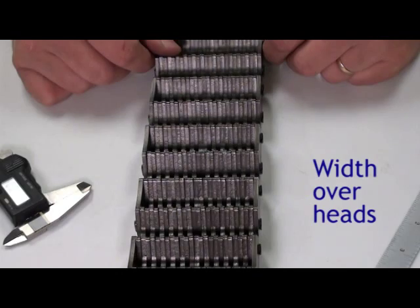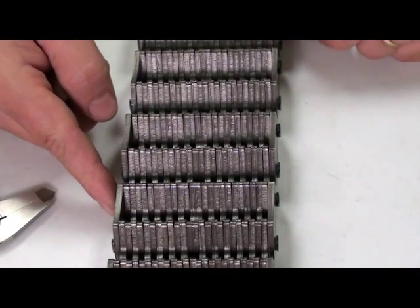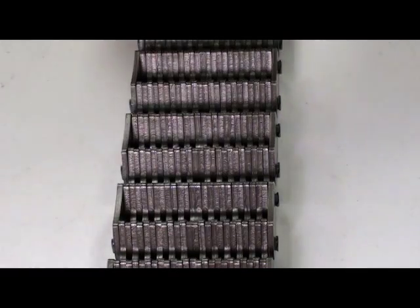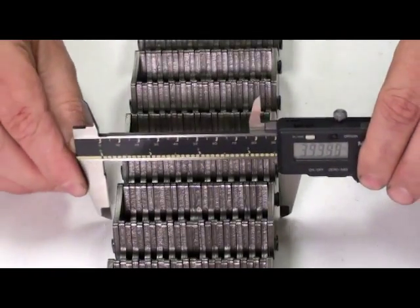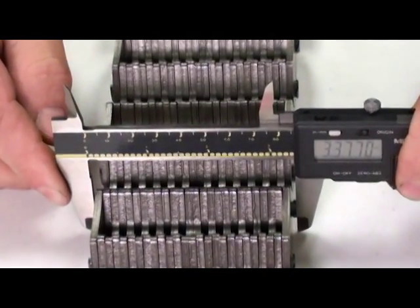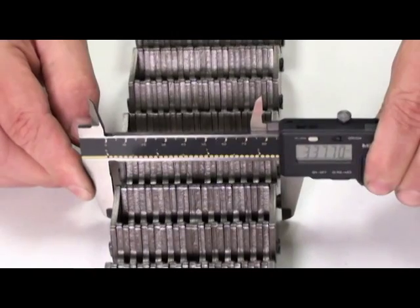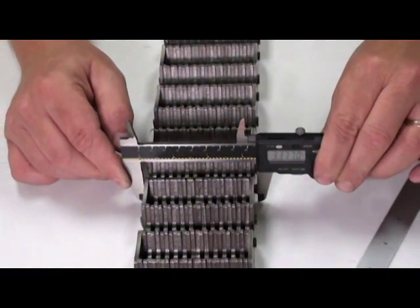The width over the heads, also known as width over rivets, is easily measured with a scale or caliper. With the chain laying on a flat surface, measure the distance across the ends of a pin. In this sample, the width over heads is 3.38 inches. The distance over the heads is typically the widest part of a chain, and it is important to assure that this width can be accommodated in your specific application.